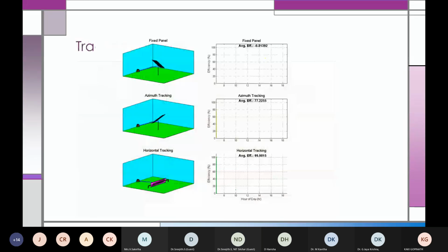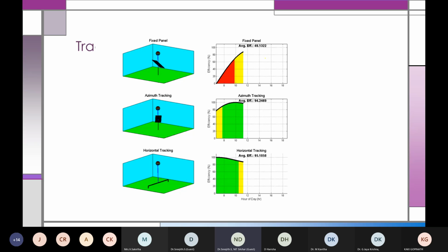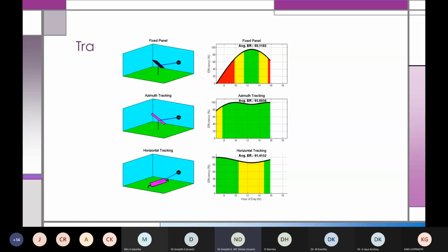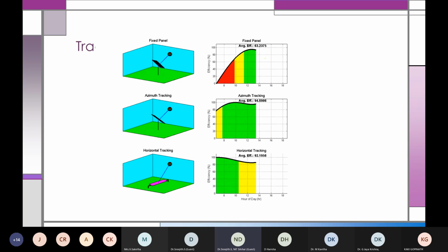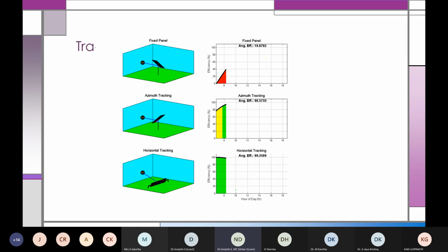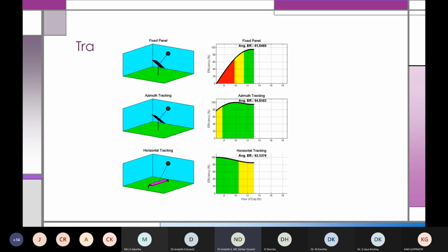And this is tracking. Tracking in the sense, assume that I have a solar panel. We have seen the solar panel is kept at some angle, a tilt angle is there. It's not kept horizontal. It is some angle tilted. But you see, the sun is not stationary, right? It is starting from one side and ending on another side. One fine morning it will be on one side, and the same day evening it will be on another side. But a solar panel is stationary in one direction only. If that is the case, the output will be very less.